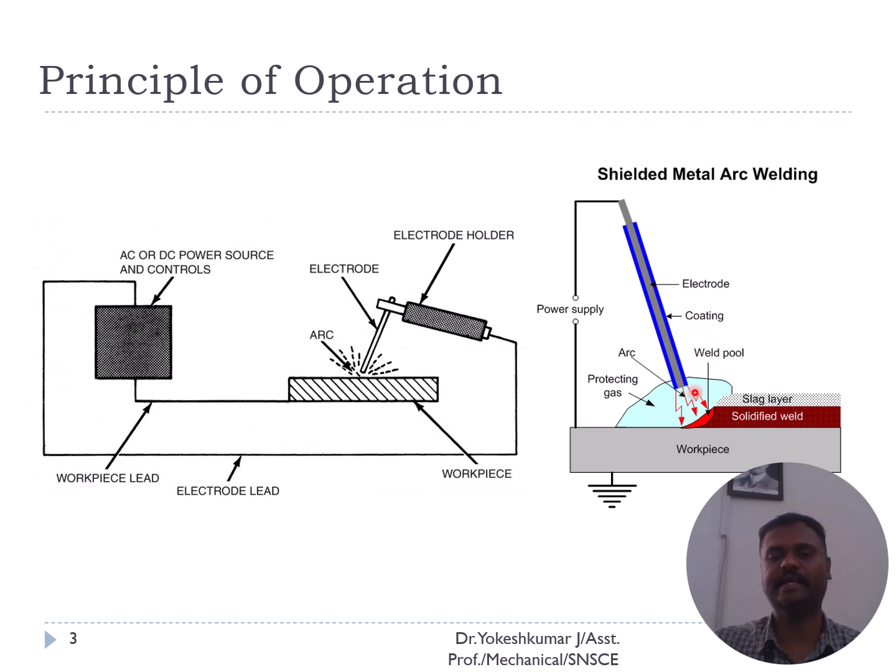That flux creates a protective gas layer which prevents the molten weld pool from contacting the atmospheric air. If the weld pool contacts the atmospheric air, the metal becomes metal oxide, which is inert in nature, so the mechanical properties of the weld joint can be degraded. Finally, after generating the arc, the metal solidifies, and we have a welded joint.